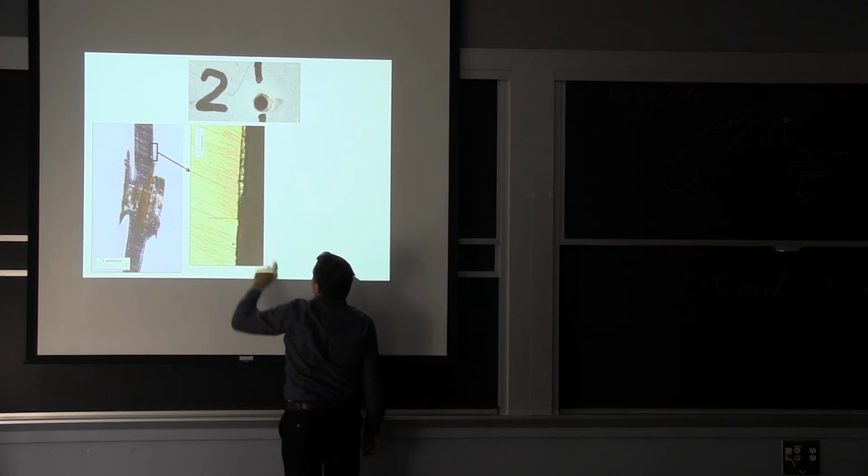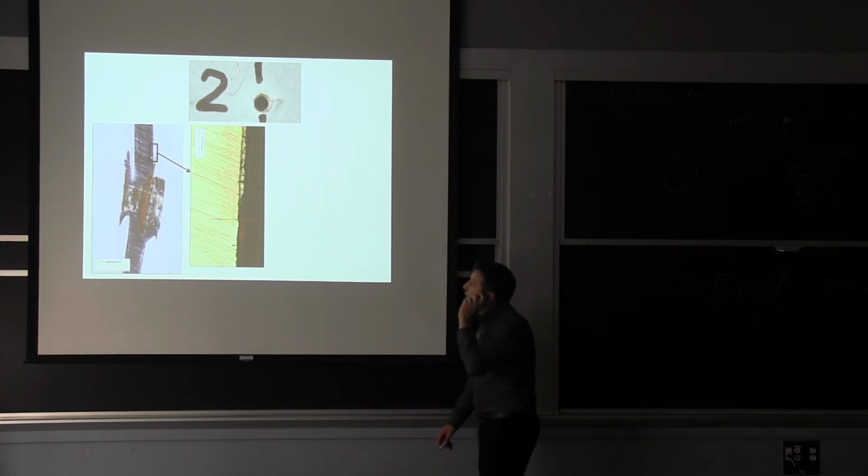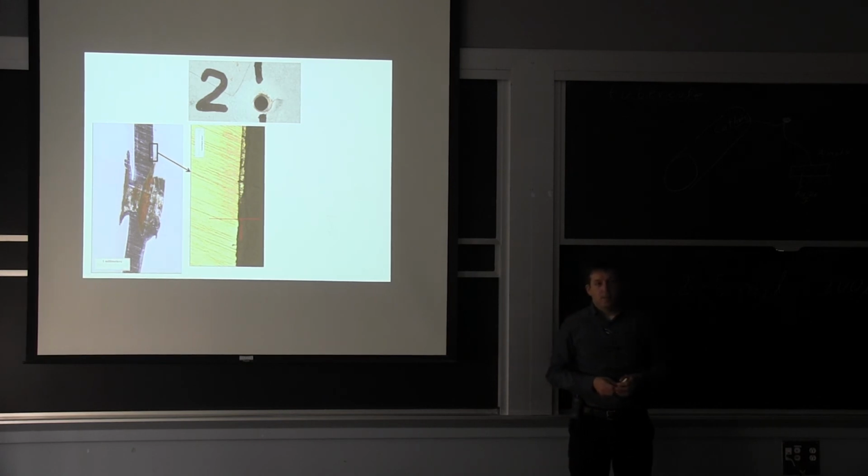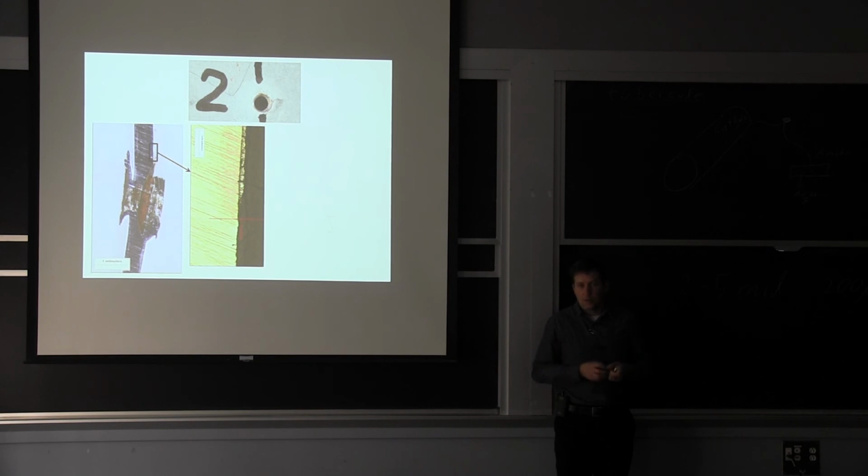But the problem is when you're far away from the hole, you're not protecting it anymore. There's a certain limit distance where you can use the zinc because of the moisture drops. You can think of it as a drip of water. As long as you can cover that same area, you'll protect it. But if it's not in the same area anymore, then you don't have the zinc as part of your environment. If the zinc is not part of the environment, then you're back to corrosion of steel.